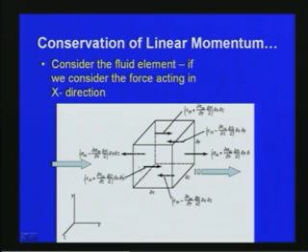So similarly on the other faces also, for all the faces we can write the surface forces for this particular fluid element. One is with respect to the normal stress on this face and the other face, and similarly, as far as the shearing stress is concerned, we can write all the components.